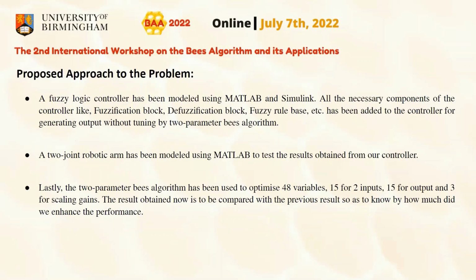Now coming to the proposed approach for our problem. Firstly, we'll be modeling a fuzzy logic controller using MATLAB and Simulink. And we'll be using all the necessary components that a fuzzy logic controller has, and we'll just create them using MATLAB. Secondly, we'll use a 2-joint robotic arm, and it will also be modeled using MATLAB. And the last part of our project will be optimizing this fuzzy logic controller by using the 2-parameter Bees algorithm.